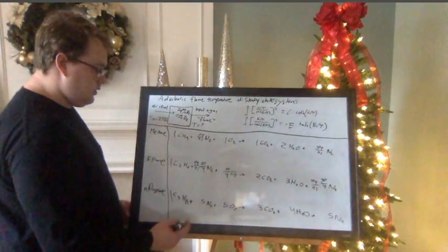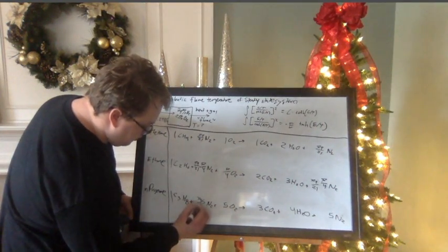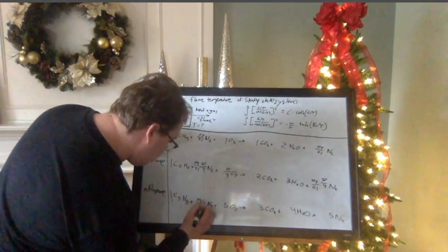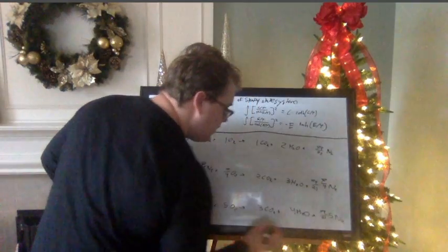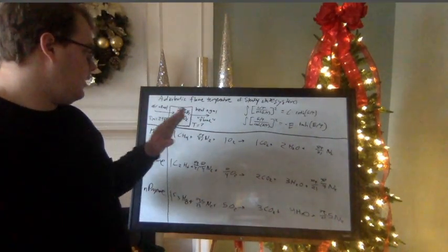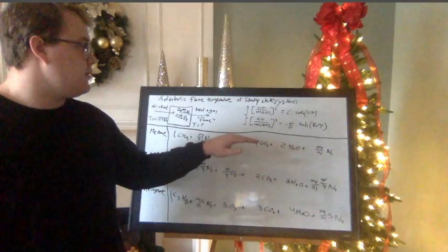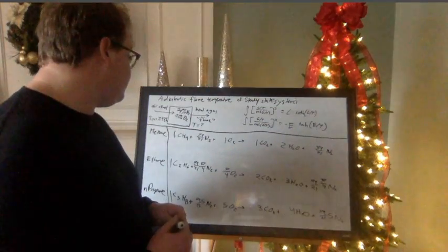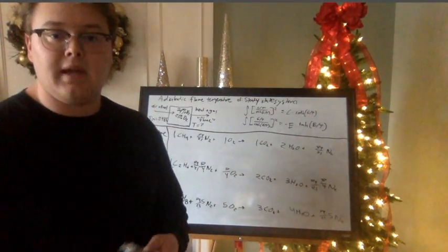And then lastly, now that my nitrogens and oxygens are 1 to 1, I can do 79 over 21 for my nitrogen. 79 over 21 for my nitrogens on my left side, and then 79 over 21 for my nitrogens on my right side. Okay, so I understand the stoichiometry of the fuels that I'm putting into my system, and I understand the integrals of my equation 107 for my specific heat. Next step is just to go into the Google Collaboratory and solve for the final temperature of my adiabatic flame.